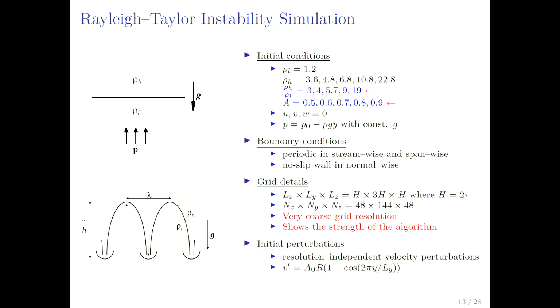Here is the initial perturbation. No, I'm talking about the mean profile. The mean profile is exponential, because if you take the Navier-Stokes equation and put in the ideal gas law, dP/dz equals rho g z, and you put in, for example, an isothermal initial condition, then you get an exponential decay in density. Density and pressure are both exponential. So you have a very drastic difference, and then you put your interface in, if it is a miscible fluid. So your Atwood number is actually the characteristic density change across the interface, and your stratification could be thousands.